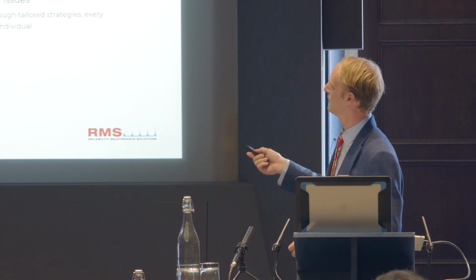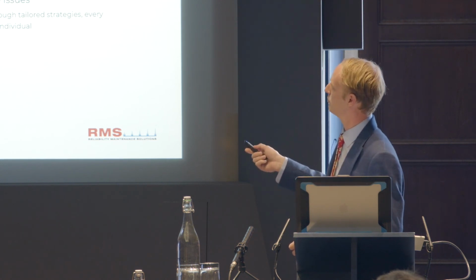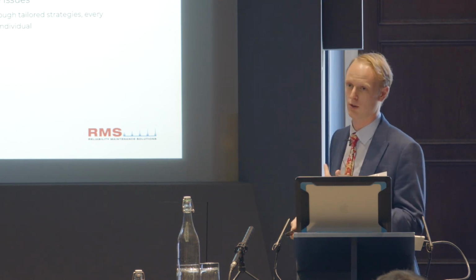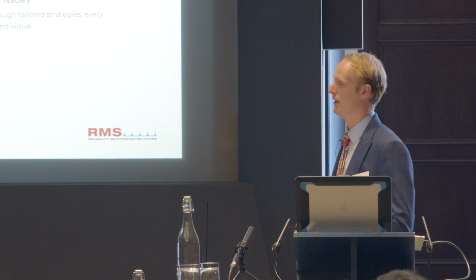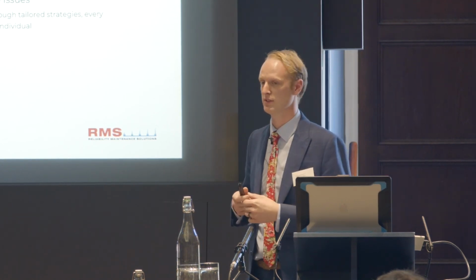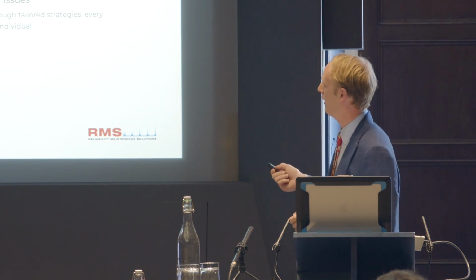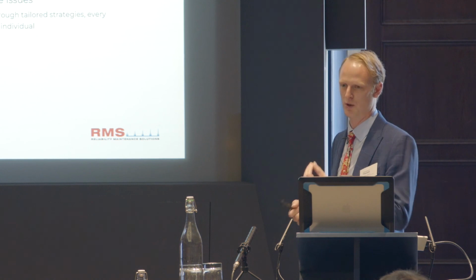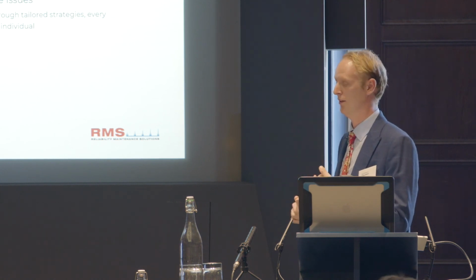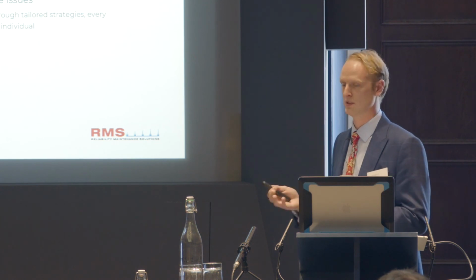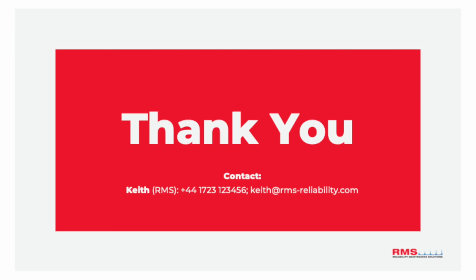We can use a variety of technologies. There is vibration analysis, thermal imaging, ultrasound and oil analysis. And there are other techniques out there that can help us monitor condition for the life cycle. And we're trying to treat machines as individuals, understand the failure modes and effects of that machine on its own. And then we can mitigate for their failures.